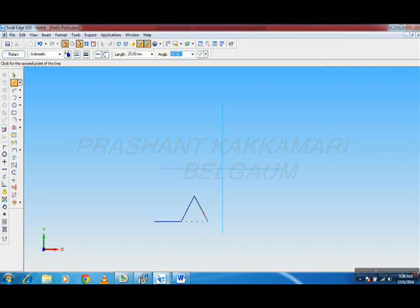Enter. Then the angle, if you are confused, just move this line towards this line. You can observe at 25 edge length it is aligned with the bottom end point. That is, again the angle is 120. Enter. Then here you can observe this length is 25, minus 180. Okay. Then see here, at a 25 length I need an angle of minus 120. Then last, the length is 25 as well as the angle is minus 60.